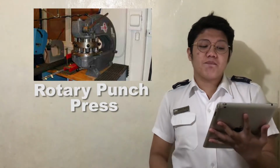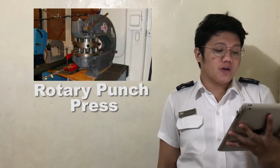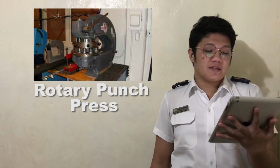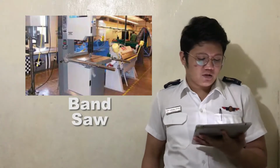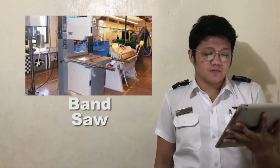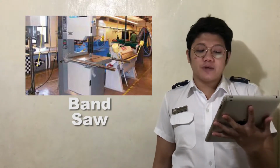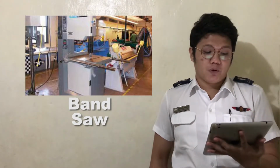The machine is composed of two cylindrical turrets, one mounted over the other and supported by the frame, with both turrets synchronized to rotate together. Next one is the bandsaw. A bandsaw consists of a toothed metal band continuously driven around the circumference of two wheels. It is used to cut aluminum, steel, and composite parts.